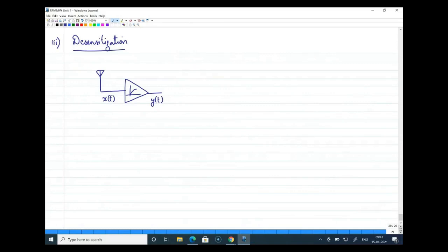All right. As I mentioned, till now we spoke only about the desired signal at the input, but we know that for an RF receiver, at the input side you will have a whole bunch of signals. It is not a single desired signal appearing at the antenna. The system is expected to process only the desired signal, but along with it you can find any number of signals, because our spectrum itself is overcrowded with many signals coming in, interferences, and many other things.